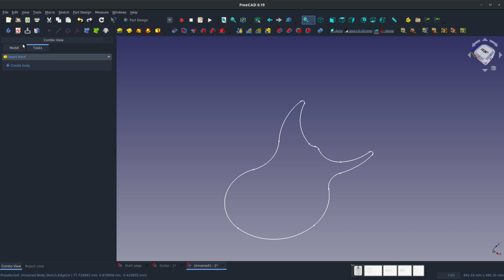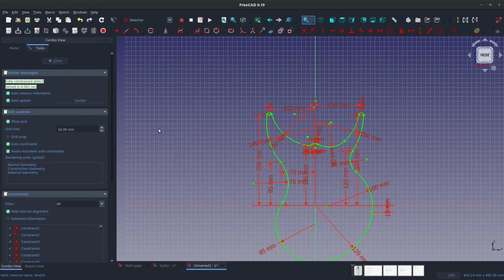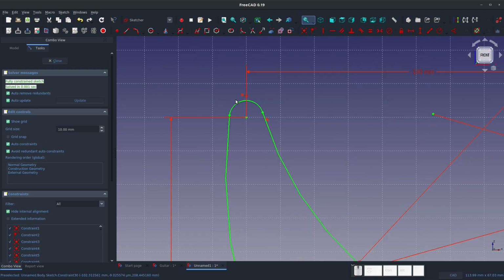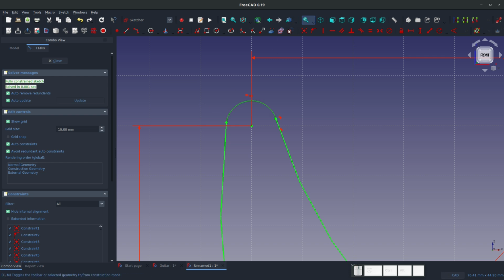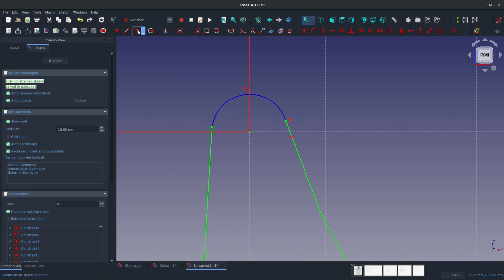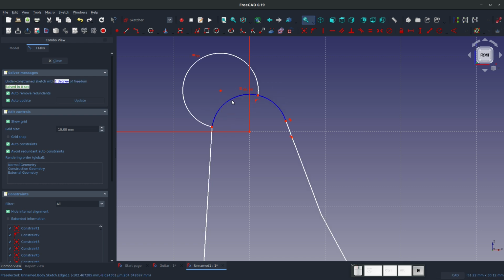First thing I'd like to do, if I actually go in and edit my sketch here, I want to take this and reference this little point here, right? So we're going to go ahead and add in another arc here. We're going to make this equal. Of course, equal in the other direction. There we go. And we're going to add vertical there.